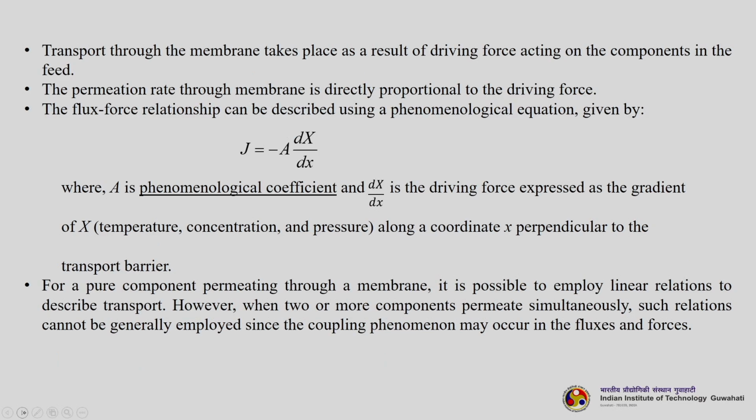Let us understand the transport. Transport through the membrane takes place as a result of the driving force acting on the components in the feed. Permeation rate through the membrane is directly proportional to the driving force. So, the flux force relationship is this: J equals minus A dX by dx. A is the phenomenological coefficient and dX by dx is the driving force expressed as the gradient of X.